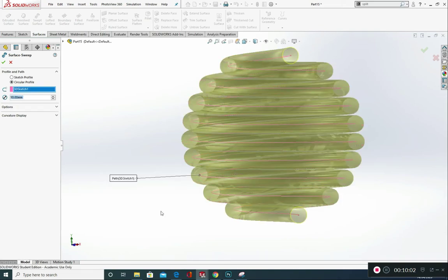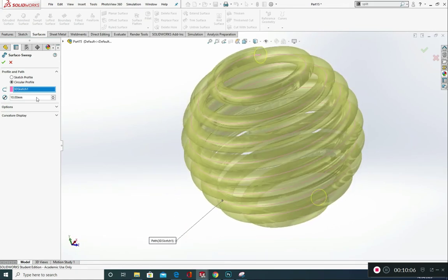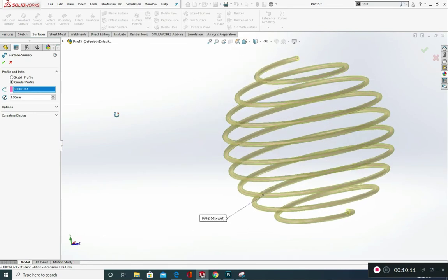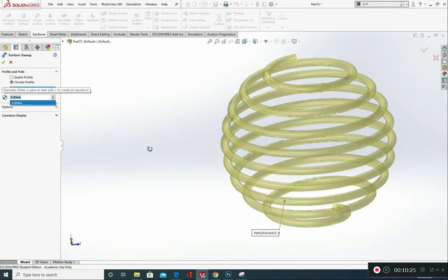Now obviously you're getting a different look here with a 10mm one. I'm going to put this in at something like 3 perhaps. Okay, you could use 5mm. If you're going to use something quite large, SolidWorks will probably hang, and it will run into difficulties producing what you've asked for if this value is too big. Okay, so I'm going to put in 3.